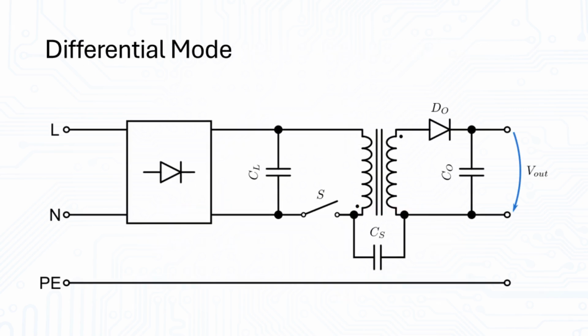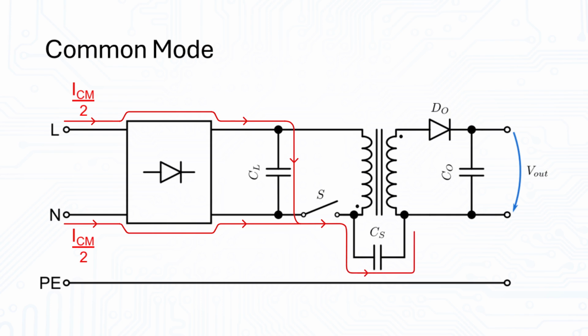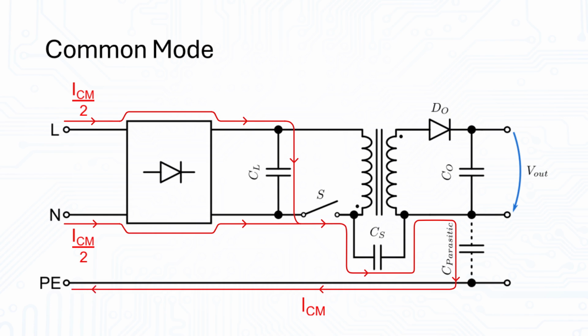Differential mode signals arise from the normal operation of a circuit. The current flows in loops from the power supply to the system and back again. A pure differential mode signal has the same absolute value in both lines, but with different signs. Contrary, common mode signals have the same phase and direction in both lines towards the electronic system. The loop is then closed via coupling into a common ground line or plane where the current returns to the power supply. Typically, this common mode current is the main source of radiated emissions.